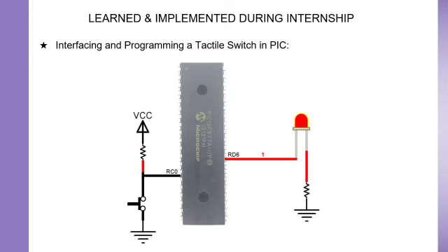When the switch is closed, the two contacts actually separate and reconnect, typically 10 to 100 times over a period of about 1 millisecond. Usually, the hardware works faster than the bouncing, which results in the hardware thinking you are pressing the switch several times. The hardware is often an integrated circuit.